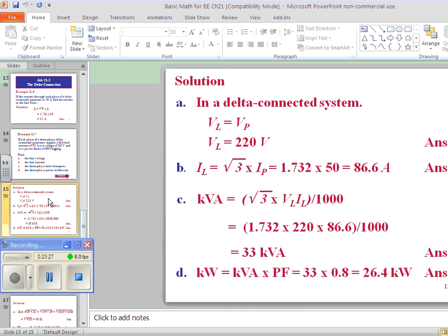Do I have to divide that by 1,000? No, not yet. Okay, then that's 32,998.0. 32,900, we're going to round that to about 33 kVA. Is that correct? But before we round anything, let's multiply times 80%, which is our power factor, to get a